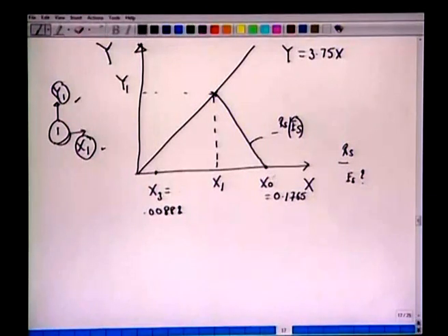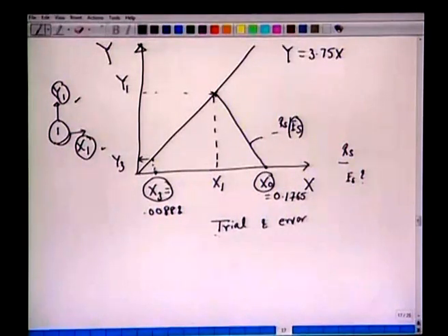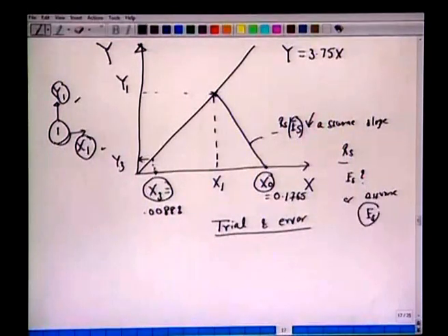We have been asked to reduce the mole fraction concentration from x0 to x3, but we do not know the flow rate Es, nor do we know y3. So all it means is that one has to iterate. It's a trial and error. We are experiencing a similar type of problem to what we faced earlier when we tried to solve mathematically. We have to assume some slope, or assume Es, which we have been asked to find out.